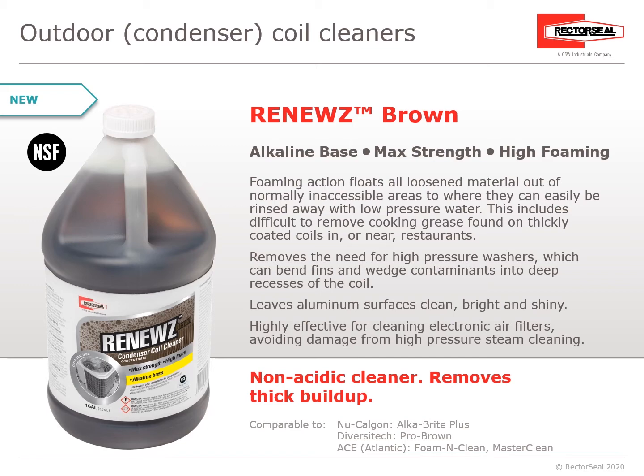It removes the need for high pressure washers, which can bend the fins and wedge contaminants into deep recesses of the coil. It leaves the aluminum surfaces clean, bright, and shiny. It's highly effective for cleaning electronic air filters, avoiding damage from high pressure steam cleaning.